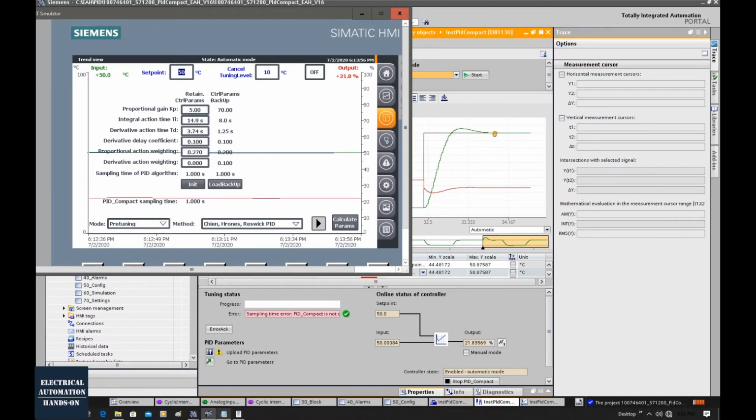In practice, sometimes a lower gain also will cause the system to be unstable because your control system is not powerful enough. So with a lower gain, sometimes the PID cannot totally hold the system. So your process system still could be very unstable with a lower gain. So that means our gain needs to be a certain value, cannot be too high and cannot be too low.